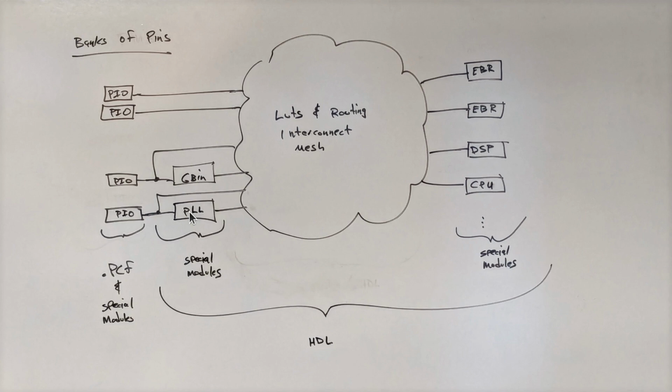Now, these things, I mark them as special because these are not things that you can see the source code for, because there is no source code. These are created directly in hardware. So what happens is the vendor tools, or whatever tool you're going to use, has to know what these are. And when you tell it you want to create an instance of a module, like I'm going to create what is normally called a top-level module in a minute, and it'll have some wires coming in and wires going out, and then it'll have its functionality, right?